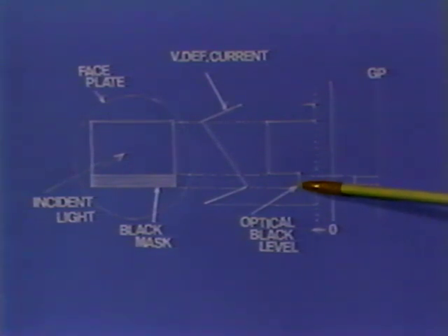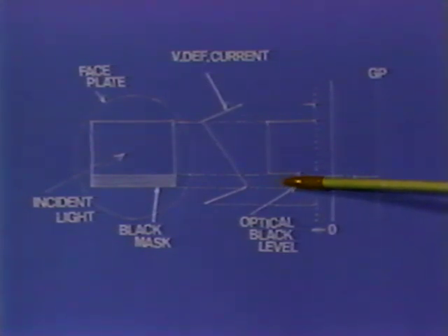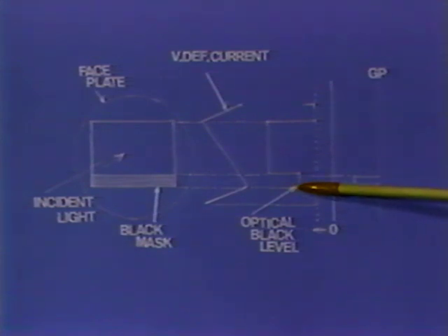The way to detect the dark current behavior out of this signal is to sample gate this part with the gate pulse like this. The increase in dark current shifts the level toward the image signal, and the decrease shifts it toward the blanking.